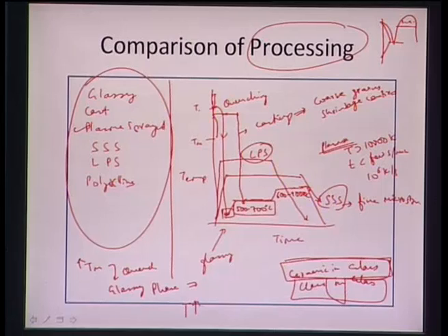As temperature is very high, but much below the overall total melting point, we will see liquid 1 plus liquid 2. So, in that case, we are seeing a phase diagram which will have liquid 1 plus liquid 2 in this particular regime, and then they tend to homogenize at much lower temperatures, but we do not let them homogenize at lower temperature. We quench them from the immiscible regime, so we can get two liquids as they are in the liquid phase. We do not let them homogenize at lower temperatures, and we retain the structure of liquid 1 and liquid 2 which were immiscible at much higher temperatures, and then we get glass in glass.